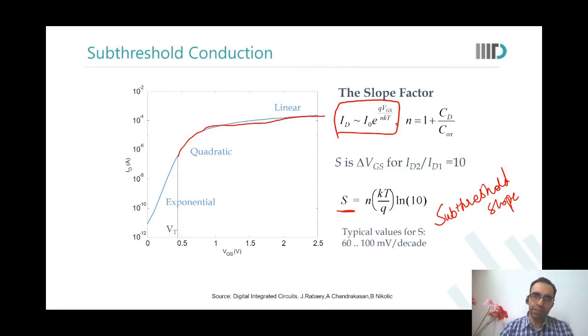Yes. It has a very different behavior. The slope is decreasing. Because initially the change of current is exponential, then it goes quadratic, then velocity saturation happens, it becomes linear. The slope has to degrade. Okay, sorry, I got confused with it.